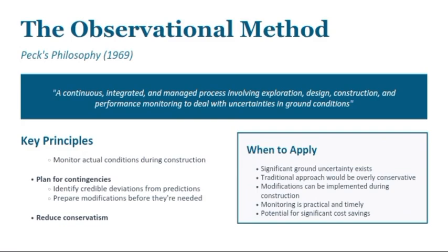One, subsurface conditions can never be known with complete certainty before construction begins. Therefore, instead of relying only on pre-construction predictions, what do engineers do? They now monitor actual ground behavior during construction. They compare observations with predictions and modify designs if and when necessary.